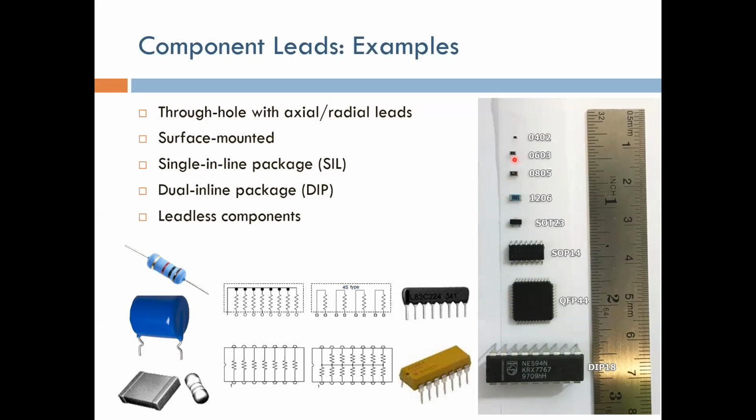You can have it as 0603 or 0402. See how 0402 looks? This is the kind of component that is used in things such as your mobile phone circuit board. You don't have that much space to put resistors of much larger size. Usually you need the large size of resistor if you have power dissipation and you want a surface area where you can dissipate the heat that is generated from the resistance.